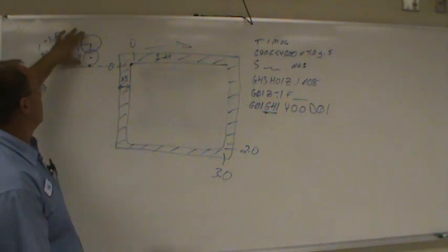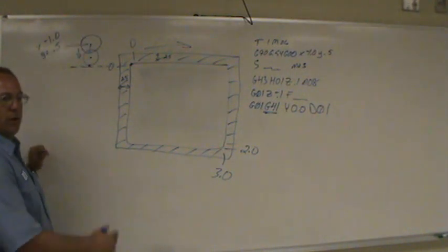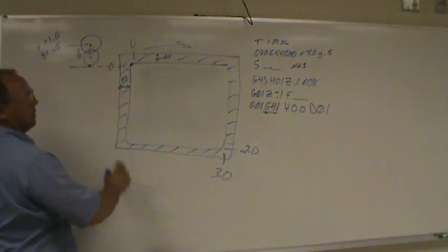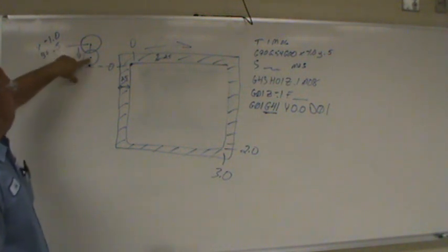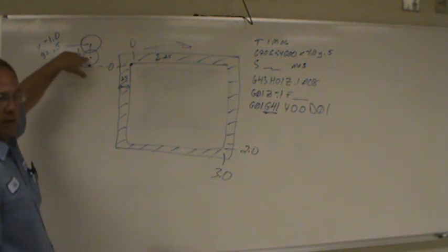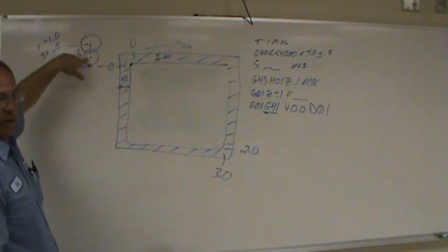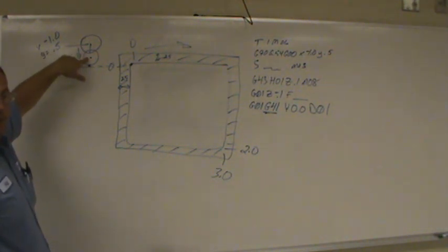And this is where the machine figures out where that needs to be. If you had a 1/2 inch cutter in here, if you look at your position page at this point in the program, it's going to say Y.25. If you had a 3/4 inch cutter in there, your position would be Y.375, half your cutter.